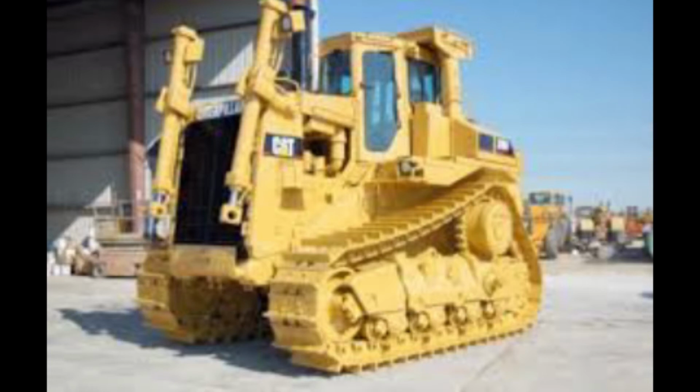Number 4, when loading and unloading, such as to unload the bucket onto the back of the truck, the loader moves forward and the arm and bucket are lifted until the bucket is above the truck. Number 5, then the bucket is slowly rotated downward until the material fills the truck. Number 6, after the bucket is empty, turn the bucket back up and back down slowly.